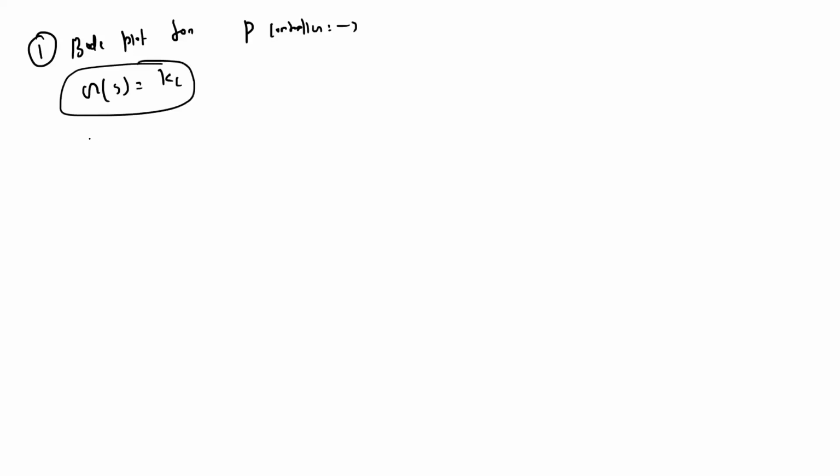Now, this was the process. Let's say Bode plot for the P controller, proportional controller. The transfer function of the proportional controller is just Kc. So the amplitude ratio will be equal to what? Kc. And phi is equal to what?